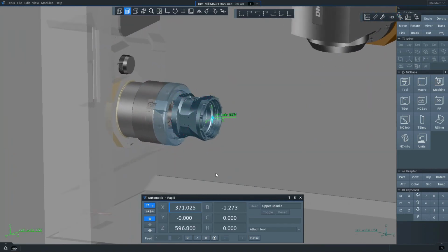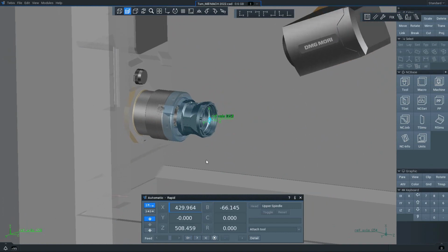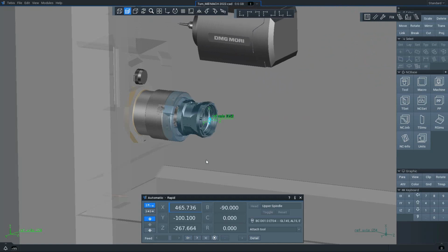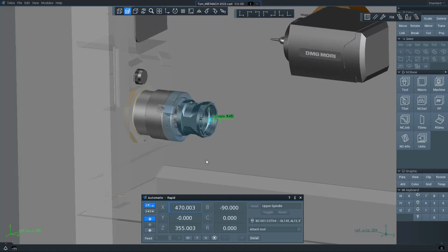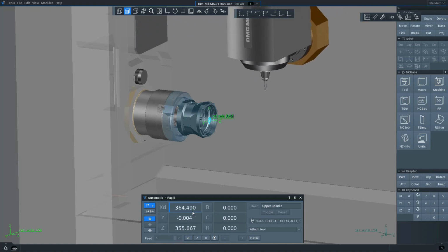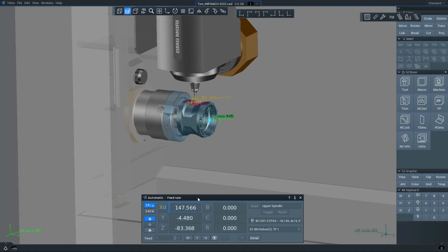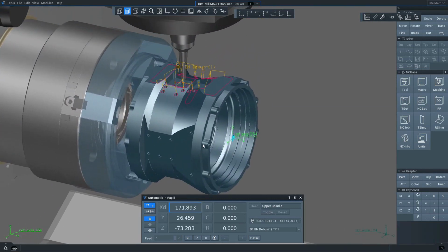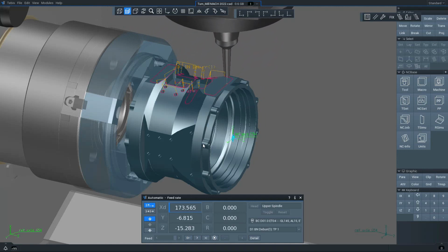what we can see is Tebis rotate the machine head, jump into the tool carousel obviously, pick up our deburring tool, create the deburring operations around the top half of the component, so these are all created without there having a necessity for a full break edge or a particular contour. So Tebis is able to create these 5-axis break edges with very little information.